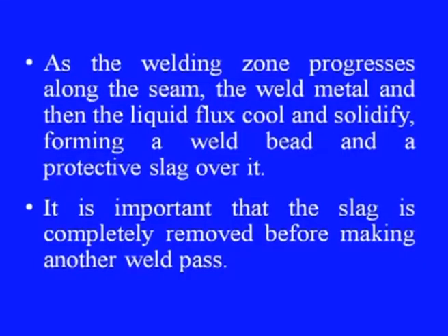As the welding zone progresses along the seam, the weld metal and then the liquid flux cool and solidify, forming a weld bead and a protective slag over it. However, it is important that the slag is completely removed before making another weld pass.